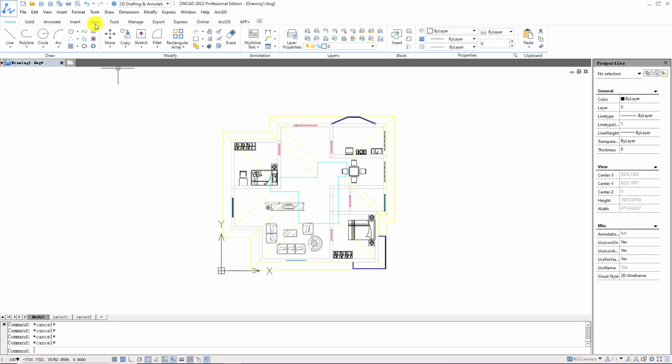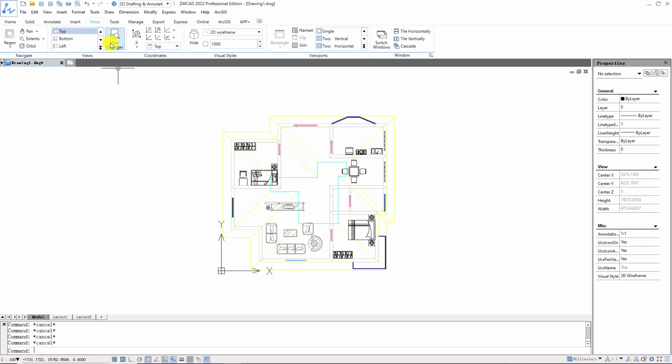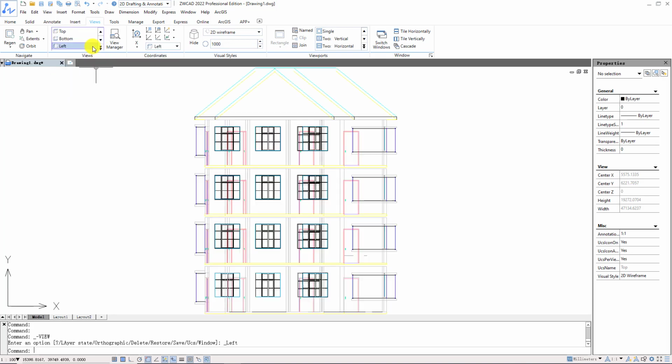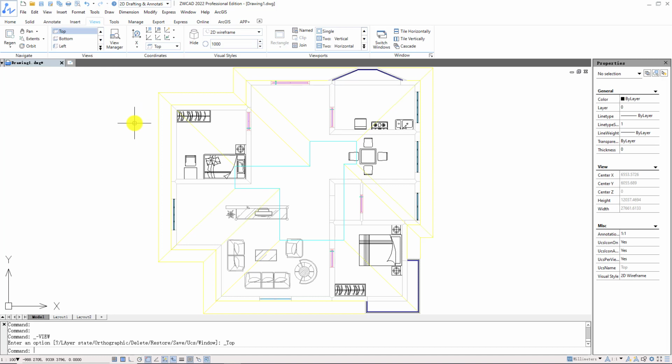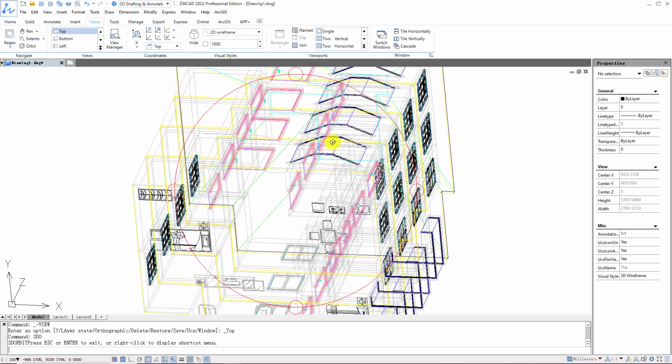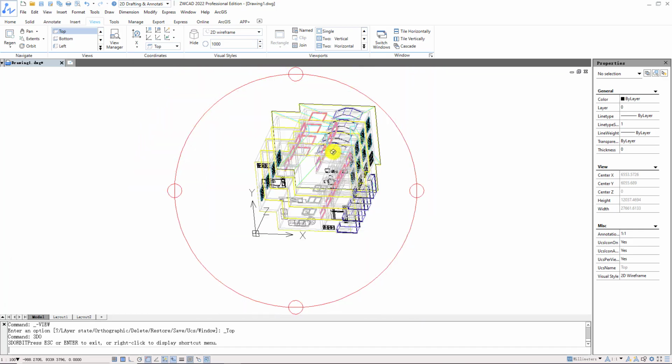First, you can find Wheel Manager in Wheels on the ribbon. There are different preset wheels provided in the menu. We can select the wheels to switch between 2D and 3D wheels. To create a new wheel, set your preferred wheel first in model space. You can zoom, pan your wheel, or rotate your UCS coordinates, or use 3D orbit to adjust your wheel.